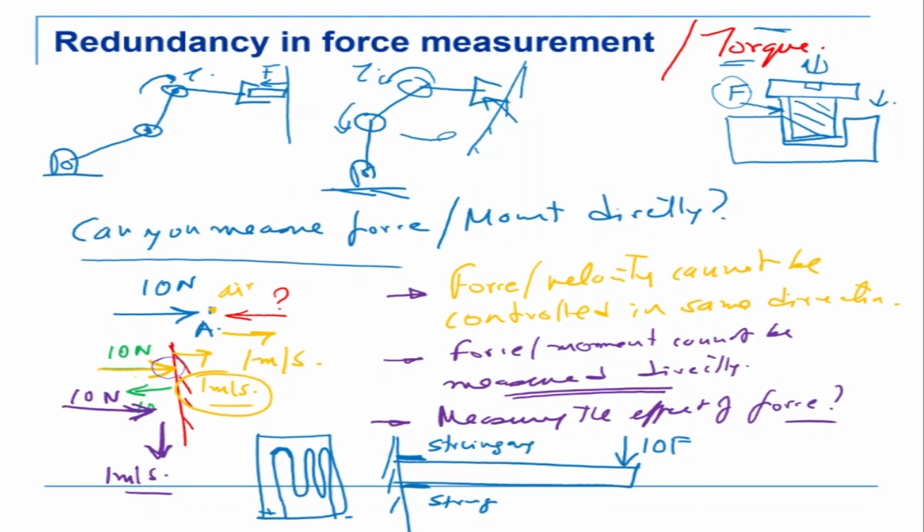So essentially, when we put a strain gauge here, this material can bend like that, and when it bends, there is a strain here. This element gets strained, and this wire gets strained, which means its thickness is decreasing, its length is increasing, and because of that the resistance of the wire is increasing.